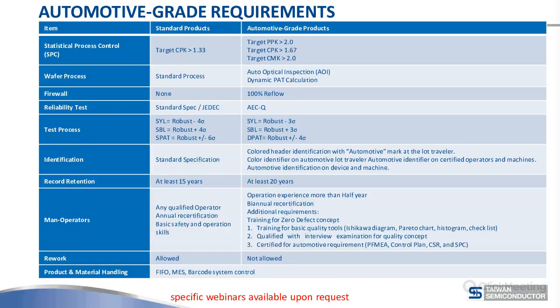This doesn't happen so much with standard rectifiers, but it happens quite often with Schottky specs. That means if you have the same product with the same distribution, you can, for a commercial part, have a better VF. You can have a VF of 0.52 instead of 0.55 in the case of a Schottky diode. And the automotive parts, with their tougher CPK requirements, may need a slightly higher VF spec to meet them. So some people say, oh, this commercial part is better than the automotive part. No, it isn't, because it will have less losses and a better efficiency. Again, you need to look at the typical VF curves to actually compare those products.